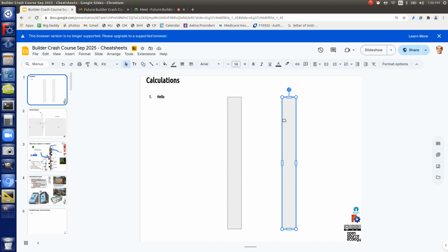And then you kind of look at it. Okay, what's happening there? They say they watered down this tool and made it thinner or whatever. So you look at it and say, well, is that steel or is that plastic? If it's steel, it's got that much strength. So you can calculate for yourself whether that item is going to break easily or not. For mild steel, when we talk about tractors, it's typically around 50,000 psi. That's the weak steel that's easy to bend, easy to weld. It's malleable, quite soft, 50,000 psi. You think about that, and you say, oh, can I use it in a frame?